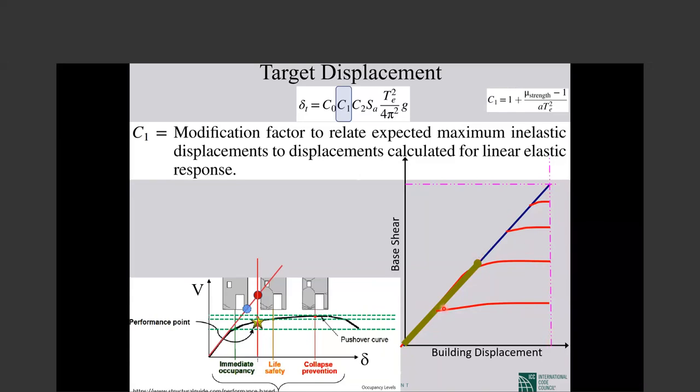You reduce its strength to much less, it gets damaged and gets this much plastic deformation. So if you let it return, it comes to here. Large residual displacement, but again the maximum displacements are the same.